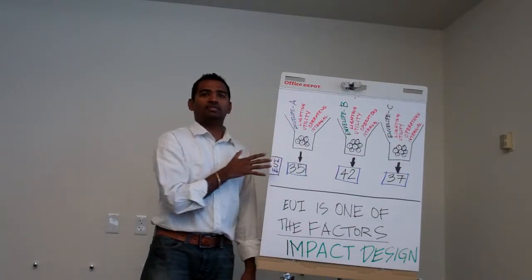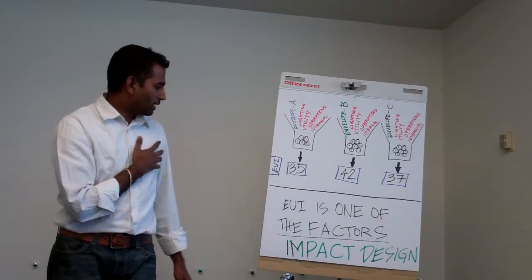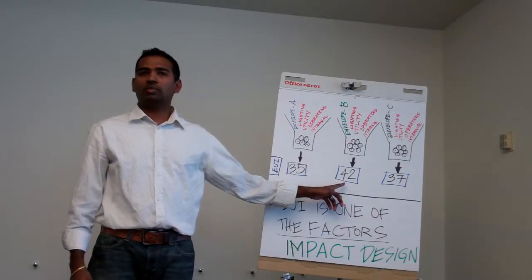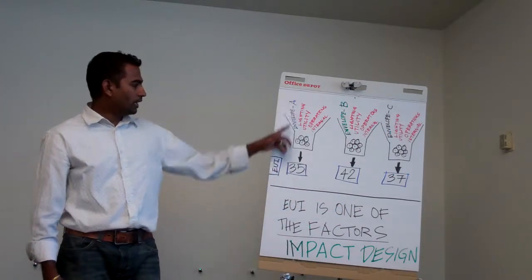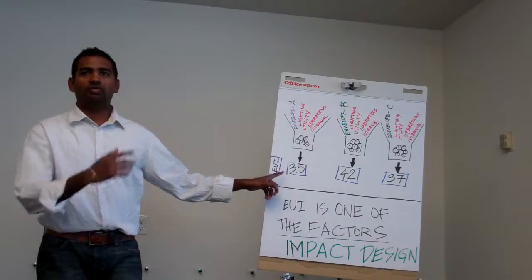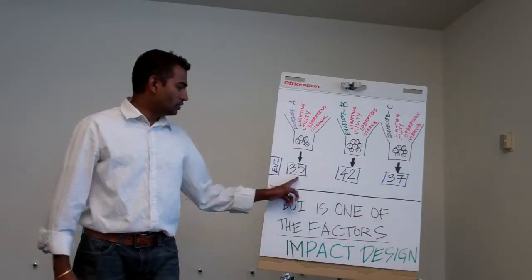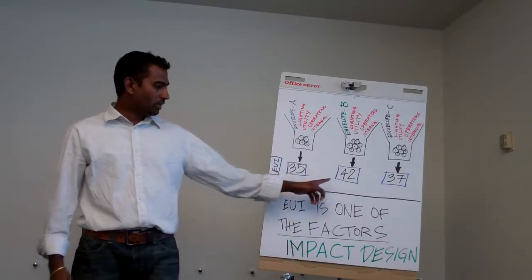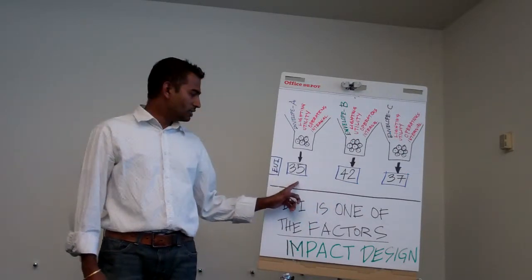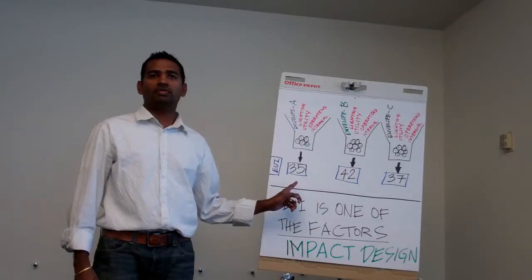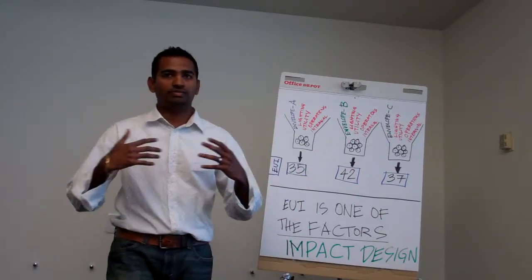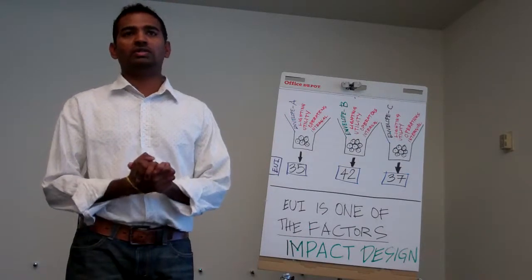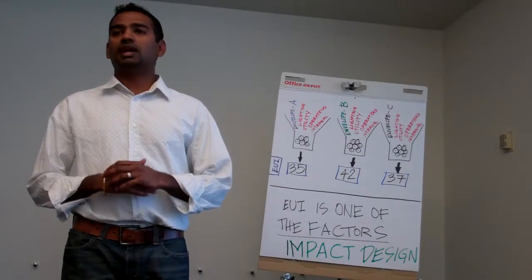So can I take this information and go to my owner, where envelope B is the standard code compliant wall and envelope A is the super efficient ICF wall, for instance? Can I take these two numbers during early programmatic design or schematic design and tell my client that I'm going to save 7 kBTU per square foot for your building, which translates into $10,000 a year? Can you say that? No. And please don't say that, because it is not accurate.